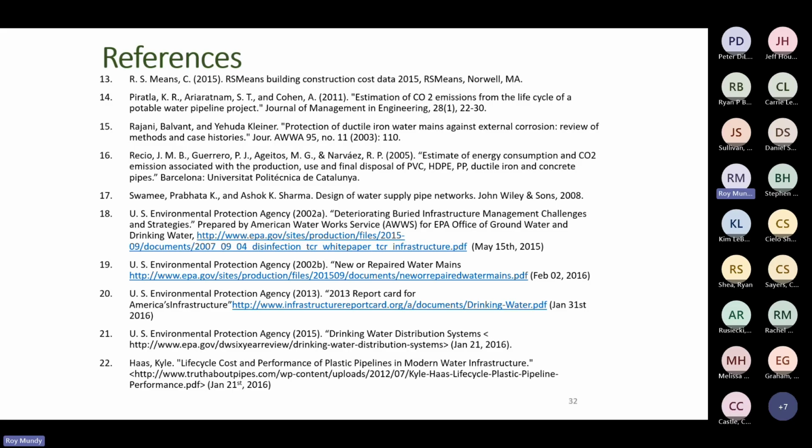So the myth is that iron pipe does tuberculate and diminish hydraulically. If the pipe is cement lined, and basically even gray iron and cast iron pipe has effectively been cement lined since the 1930s or so, then you're not going to see any diminishment of the C factor.